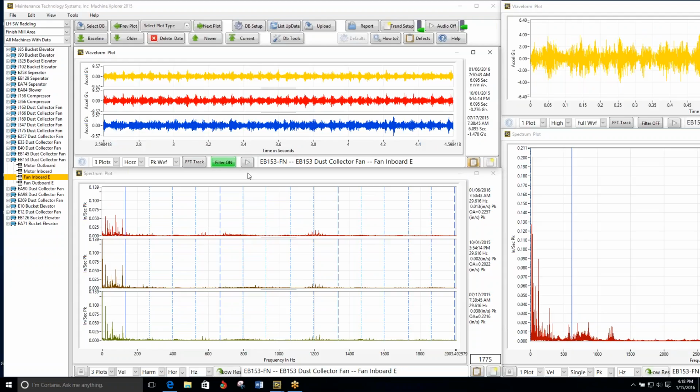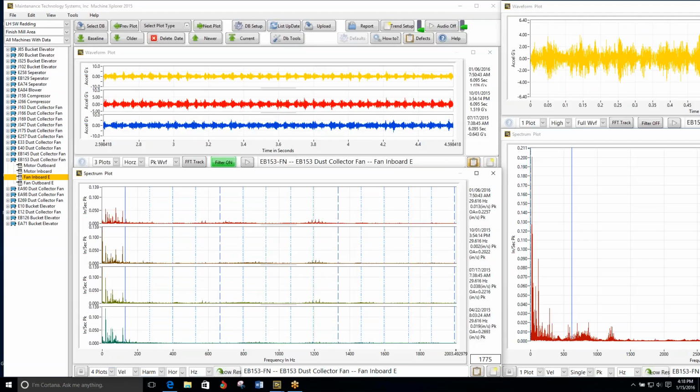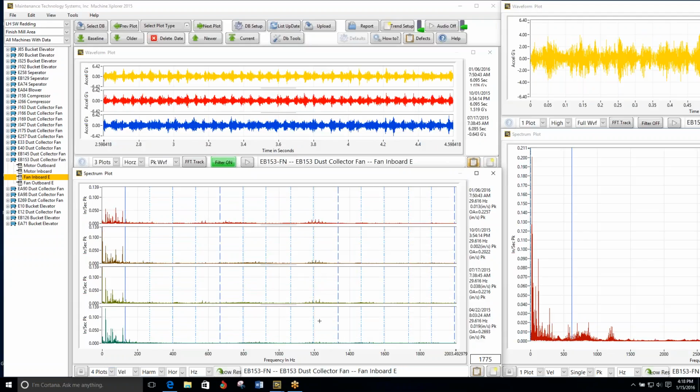It's got a little kick going on that motor. Yeah, but not a lot of change. Look at these bearing patterns out here. They're coming up a little bit, but we're still well below 0.1. Change that to acceleration. Which one here? Yeah. Okay.